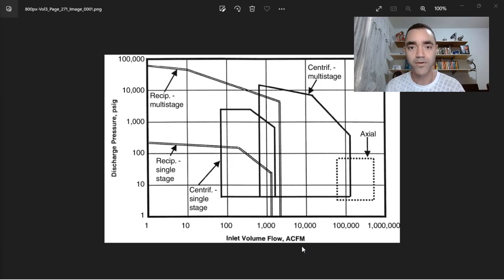So when we have a compressor or a rotating equipment that is identified by the actual cubic feet per minute, it means that the process conditions for pressure and temperature are your operating conditions. If it is 40 Fahrenheit or 15 PSIG, it will be the conditions for the actual volume flow. And it's important because when you do the conversion to normal cubic meters or standard cubic meters, the values can be very, very different. So this is the first point.